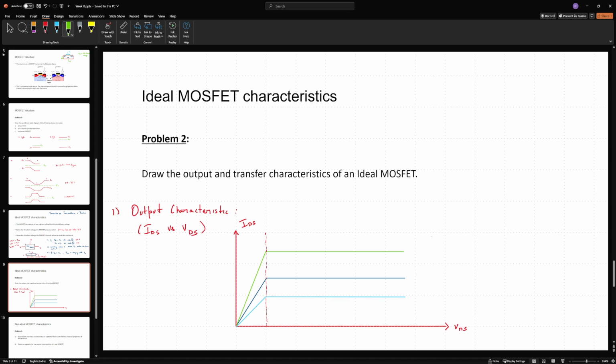So this is my device operating at VGS1, at VGS3 all the way down, and VGS2 here. So these are the variable resistance values and the current seems to be plateauing. Now first question is, what is the relationship between any of these VGS and VT? Now the channel, the drain source connection, is acting as a fixed resistance value for one of these VGS values. So the first thing that I can say right off the bat is that all of these three VGS values are greater than VT. They are greater than the threshold voltage.